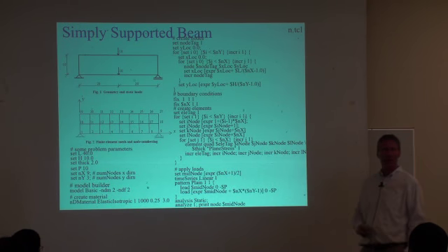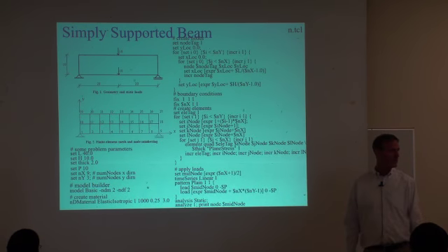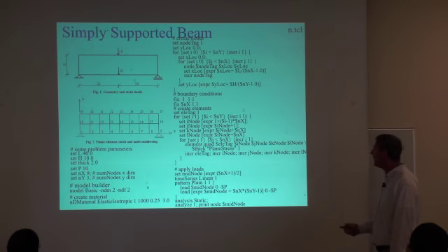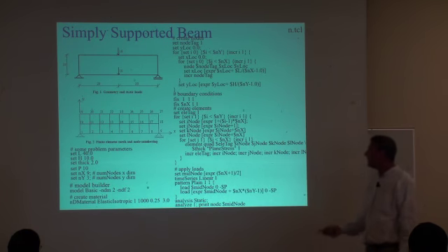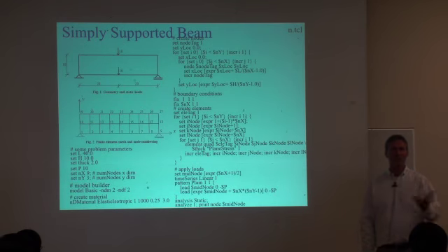As I say, when we're doing continuum models or any type of models, if we can start using these four statements, we can actually build a model very quickly. And that's exactly what I'm doing here. So basically, if I want to change the discretization of this mesh, I don't have to issue all the different node commands. All I have to do is change the number of X and the number of Y. All I do is change these 2 points here. The discretization is handled in my loops where I'm creating the nodes and I'm creating the elements. Okay? It's the power of this scripting language that you sort of have to use to really appreciate.